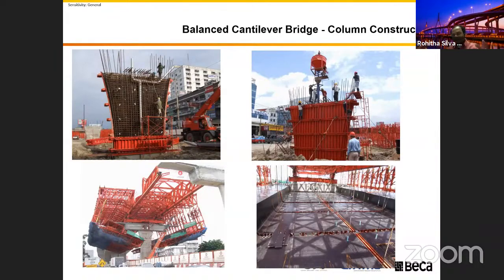And if you look at it in terms of loading, we all know when you have concrete, it creeps and shrinks. So all this timing and ages will affect your design, because in your bridge, during construction and even after you finish, you have different ages. Each and every element in the bridge has a different age. So the creep and shrinkage on the bridge have different strain levels or different forces. That means it's time dependent. Forces will vary all the time.